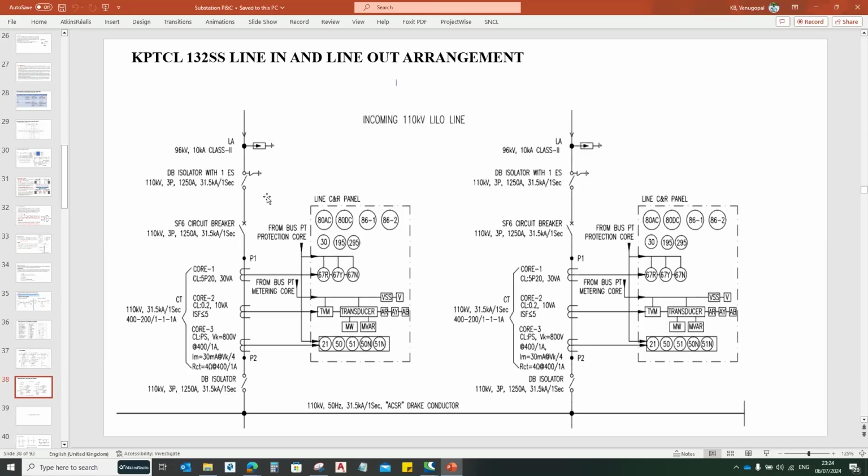Because with these faults, you have to sense the fault with the higher fault current. Transient faults will be there and permanent faults will be there, but transient fault currents can be in terms of kA, like 63 kA, 100 kA, 150 kA, sometimes. So you have to find that fault current, then only your relay will operate.